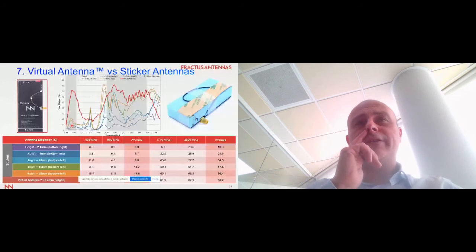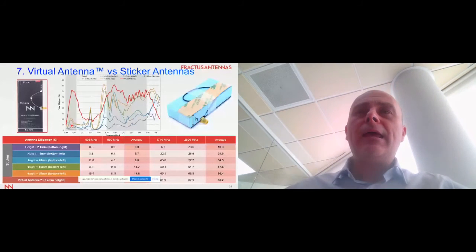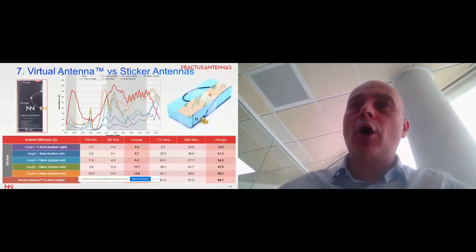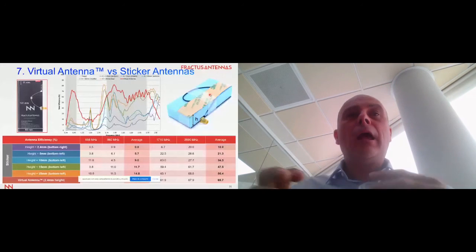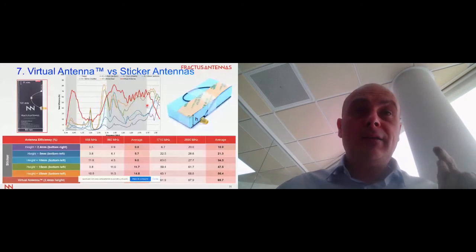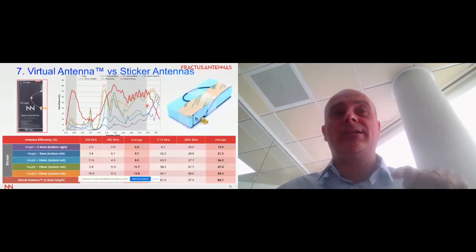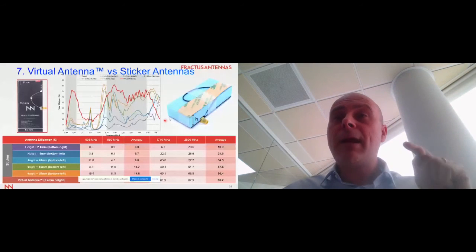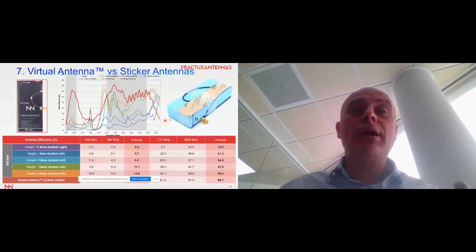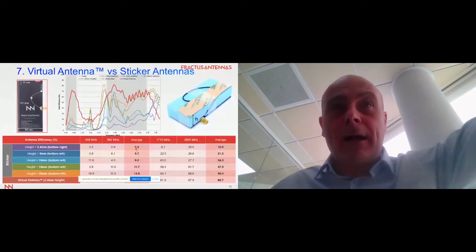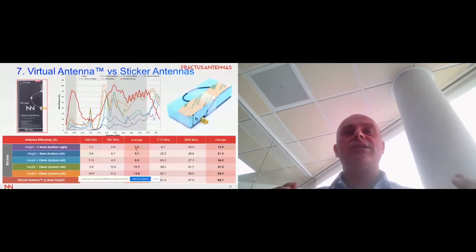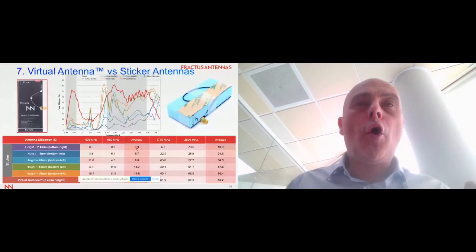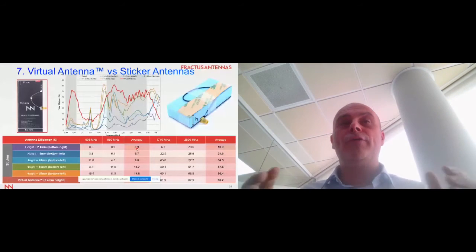Another issue we detected with the sticker antenna is that when mounting it in several positions, the performance changes. In this graph, we are illustrating the best cases. But if you have the same height and put it in another position, you can get even worse values. So this is very sensitive to how you mount the sticker on the device.